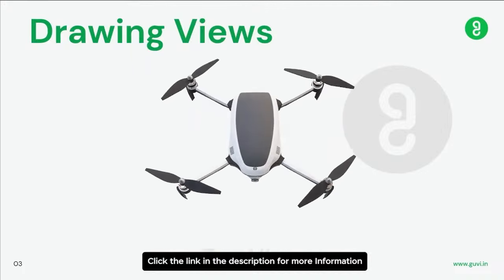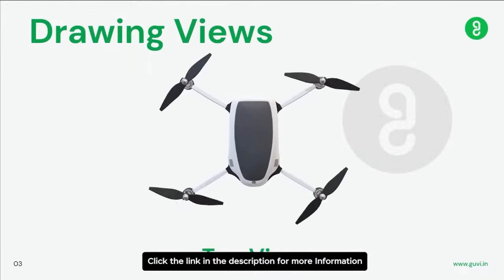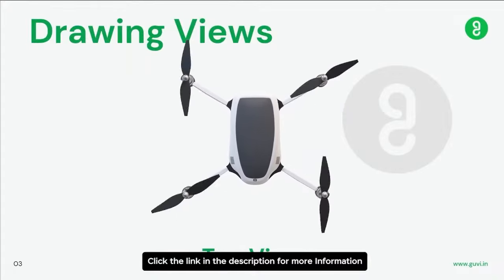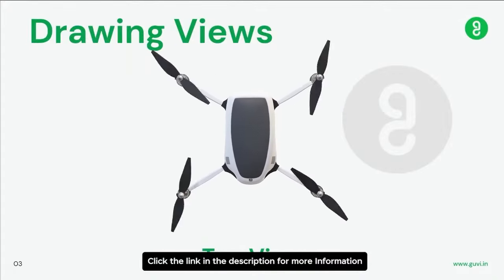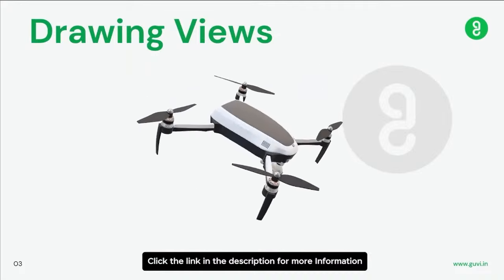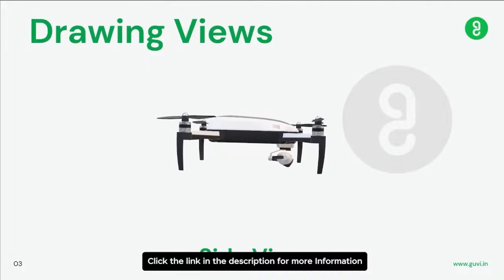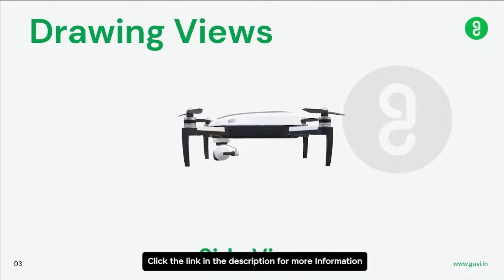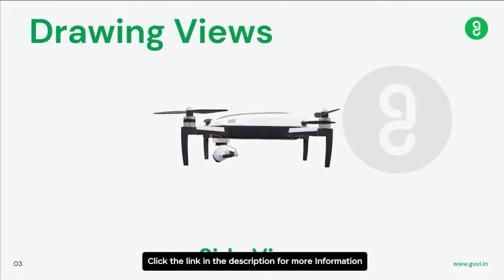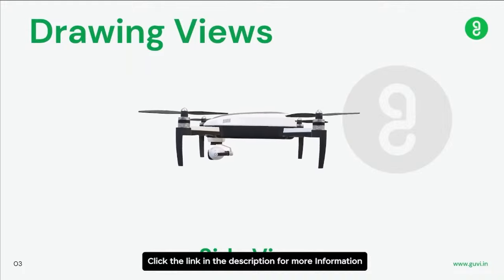Then comes the top view. Another view which is seen from the top, looking down on the top face of the object. It provides information about the object's width and length, and helps us understand its overall shape and symmetries. Then comes the side views. In the side view, the object may be seen from the left or from the right, depending on which side the designer chooses. These views provide information about the object's height and depth and help us understand its cross-sectional features and profiles.